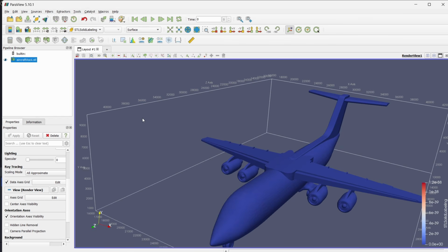It happens because when you export any STL file from CAD modeling software, it takes the dimension but replaces the unit with meters. Probably this was designed in millimeters, but then it was changed to STL and it assumed all the millimeter values are in meters, which is not realistic, right? So what we are going to do is scale this down with a factor of about 1000, so we are getting it in meters instead of millimeters. So whatever is 40,000 meters will become 40 meters, which is a realistic scale.